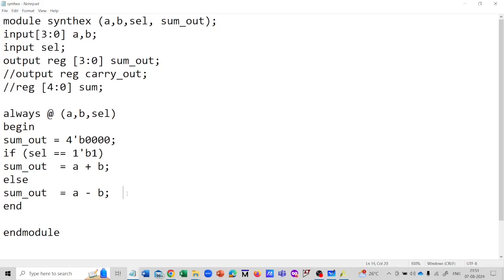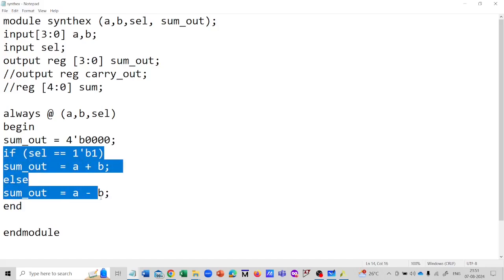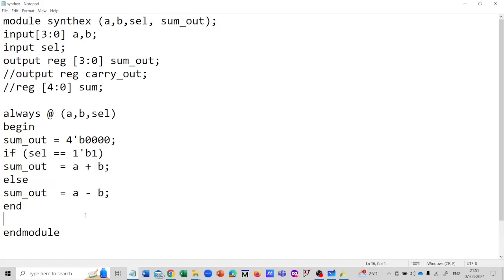So you can see that this is a rudimentary ALU. And from the if then else structure, it is also obvious that a mux will be synthesized from this code. The basic template is that of a mux, and the two inputs of the mux will be from two different arithmetic modules. So that is what we can infer from this small block of code.